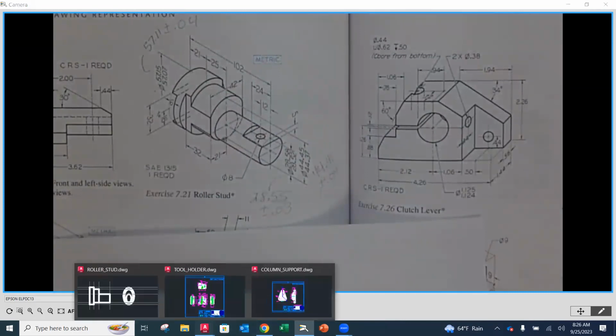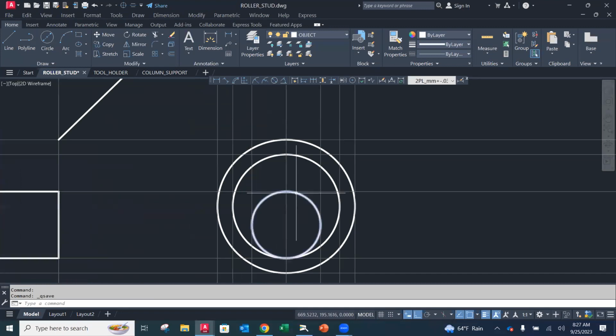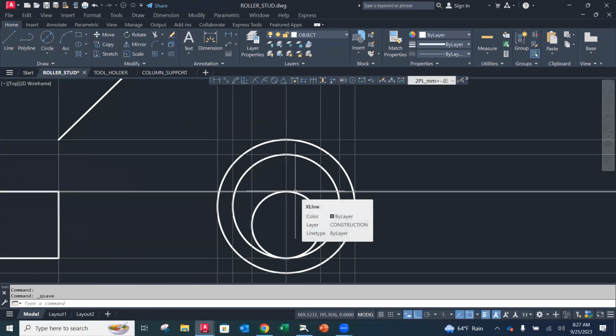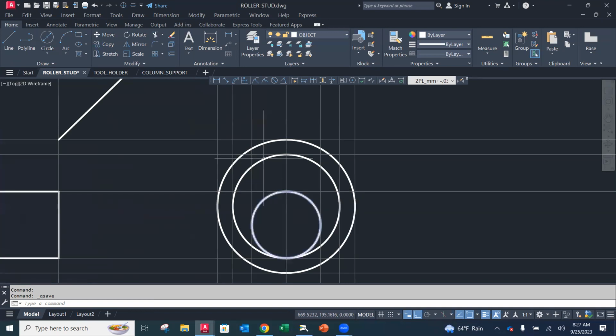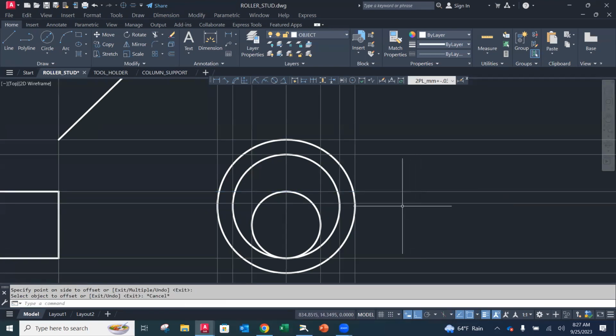So going back to AutoCAD, I'm actually going to set that one up in the right side view, because I need to know when I go 5 millimeters deep, where it lands on the two sides here. So I'm going to do an offset. Okay. 5 millimeters. I'm going to use the construction line and go straight down. Okay. And I'm on my object line layer. So I'm just going to simply put lines from the intersection that was created by that construction line on either side.